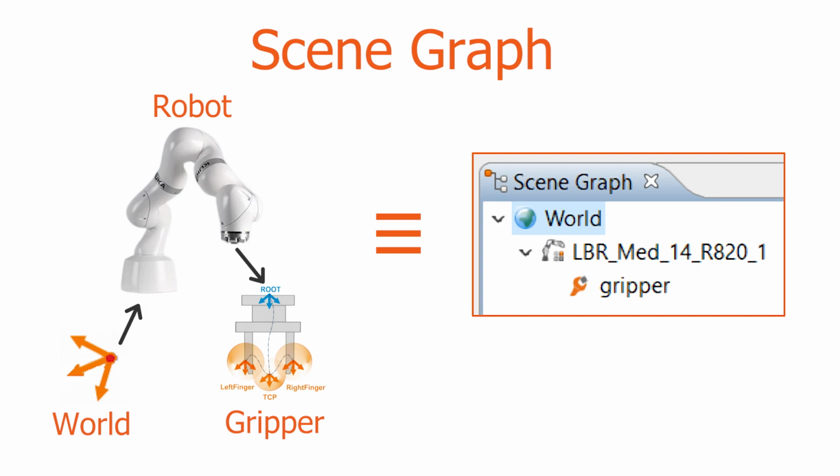Non-transient objects can be created within the scene graph by means of an object template. However, it is very important to note that the scene graph is only taking a snapshot of the object template. Therefore, any changes made in the object template will not be reflected in the scene graph object after it has been created. This would require you to delete the object out of the scene graph, make your change in the object template, and then re-add the object in the scene graph.